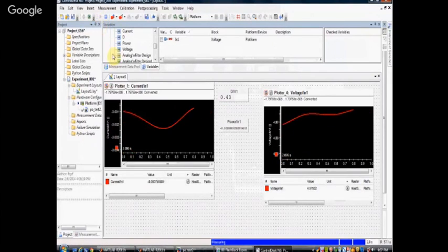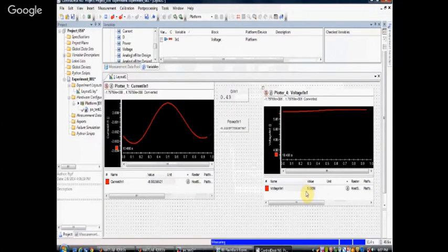So this value is a real-time value, which is coming from my PV panel. I can see here the voltage is 5 volts now. But this is according to the room condition. I have not turned on my halogen lamp. According to the irradiation of the room, it is 5 volts and the current is 0.002 mA. In the sense, current is not flowing through the system.